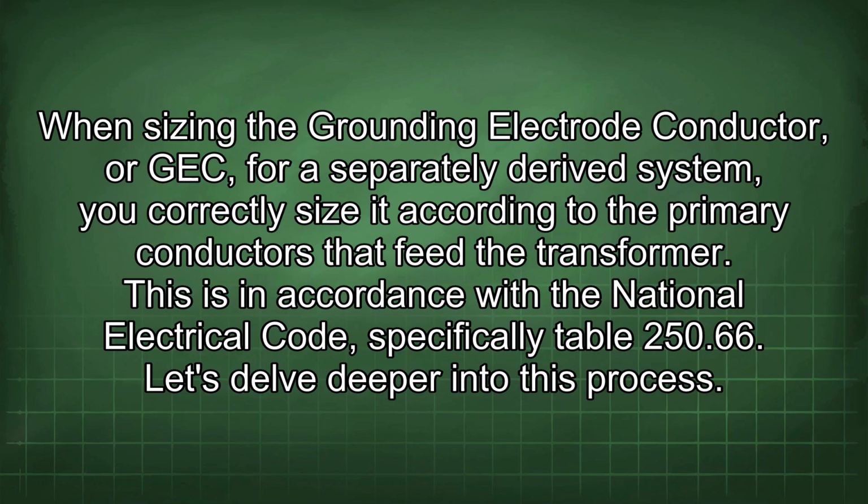Size in the grounding electrode conductor, or GEC, for a separately derived system, you correctly size it according to the primary conductors that feed the transformer. This is in accordance with the National Electrical Code, specifically Table 250.66. Let's delve deeper into this process.